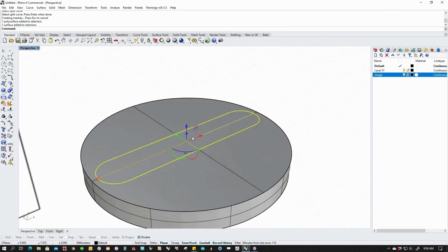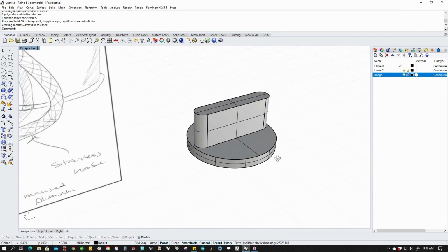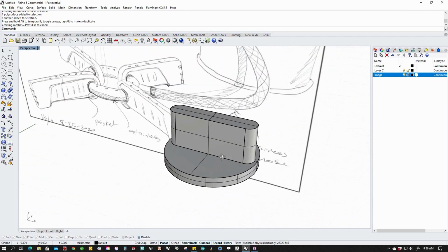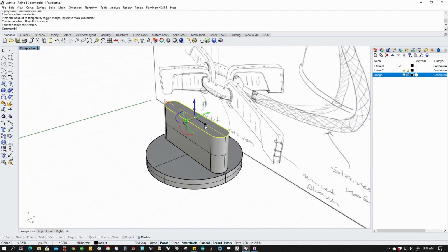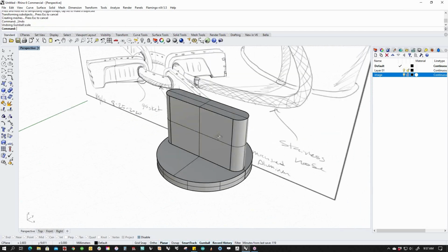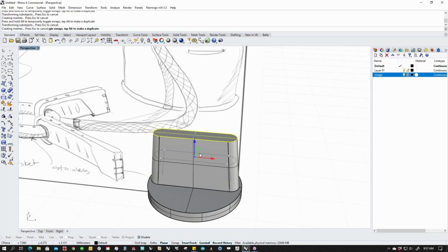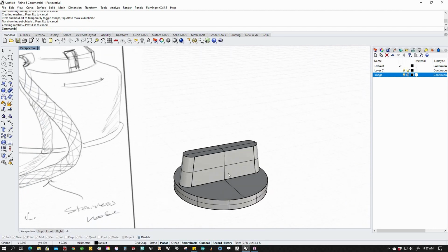Shift control click, drag the extrude dot, insta knob. Cool, huh? And because it's a degree 1 object, I can adjust it. I can say it's bigger, smaller. I can do things like that. Actually, I don't mind that. Let's give it a little of that. It's too tall. And that gives us our little knob.